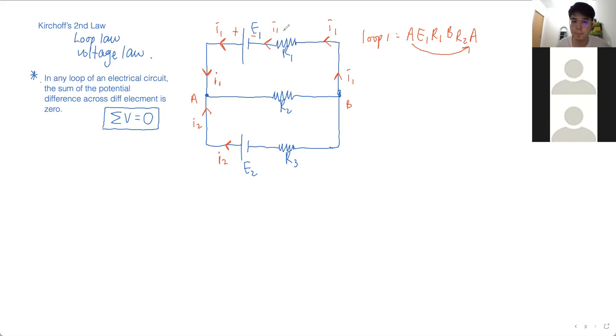Now this branch, the upper branch: I just said the current is the same in the same branch, so from here to here it is all I1. The I1 direction just follows along. From here it flows here, and it is the same with I2, and here is also I2. How about the branch at the middle? At the middle branch, this one enters, this one enters. So the current leaving here is I2 plus I1. On the other end here also I2 plus I1.